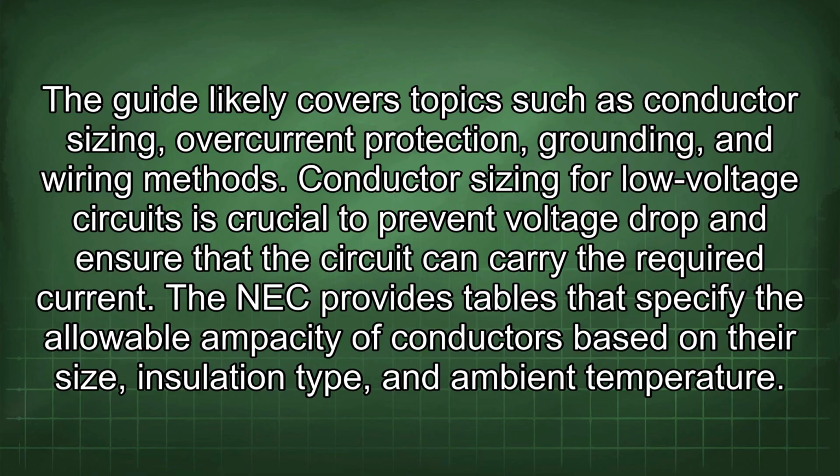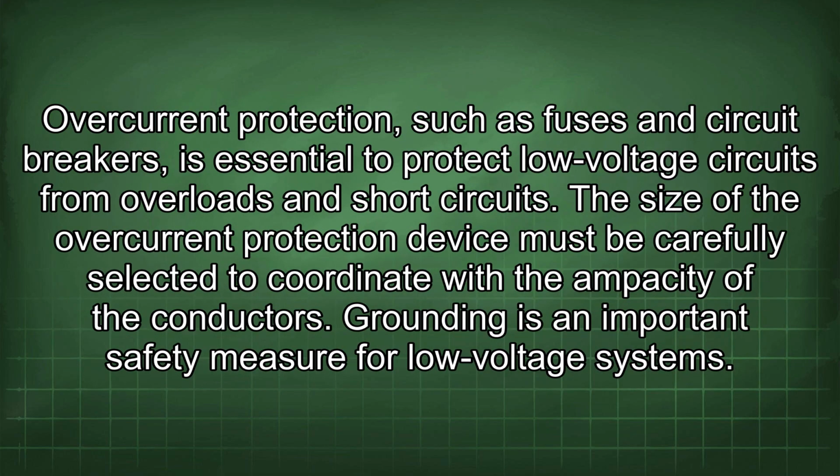Conductor sizing for low voltage circuits is crucial to prevent voltage drop and ensure that the circuit can carry the required current. The NEC provides tables that specify the allowable ampacity of conductors based on their size, insulation type, and ambient temperature. Overcurrent protection, such as fuses and circuit breakers, is essential to protect low voltage circuits from overloads and short circuits. The size of the overcurrent protection device must be carefully selected to coordinate with the ampacity of the